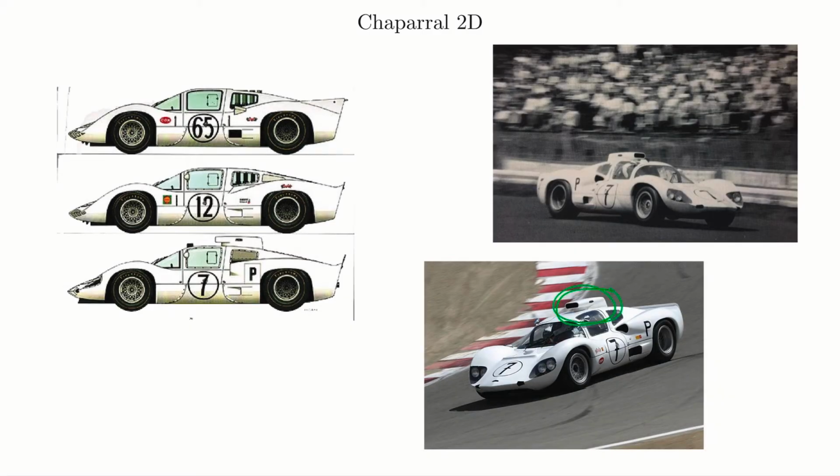It's also added the ram scoop at the back, okay? And that was a nice innovation because, again, it's another use of air over the vehicle, right? This is what Jim Hall as an engineer is capable of doing. He takes the air over the vehicle, and when you take that high velocity air and slow it down, you get a high pressure. So the ram scoop's able to take that high pressure air, and you now have high pressure air that you can feed down into your engine.